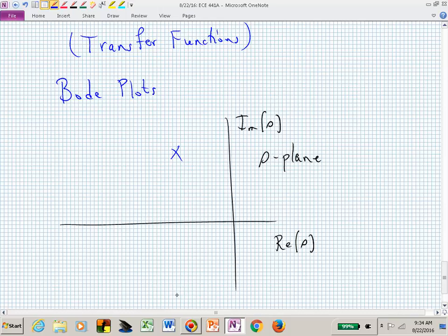Maybe our system has 3 poles, and the poles we will represent with X's. Zeros will be open circles. Here I haven't indicated any zeros. We will start to learn how if we put this system into a closed loop, we fed back the output and cranked up the gain, we will start to understand what the system will do via a root locus.